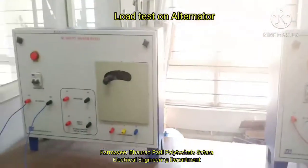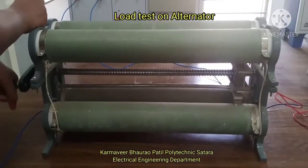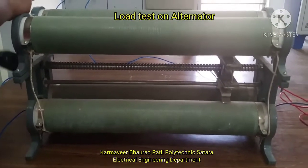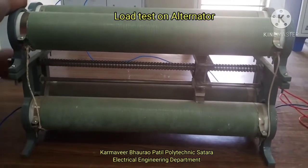Now on the alternator side, excitation supply on, increase the excitation till the time it shows the voltage about 350 volts.